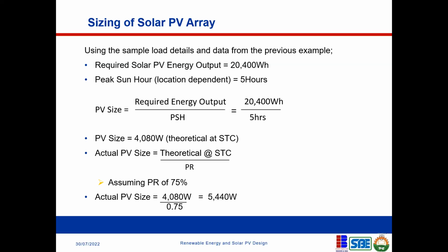So their performance drops by 0.5%. Some of them can be 1%. So every year, the performance of that PV drops by a certain percentage. The equipment manufacturer will always provide this information. It is not the same for every PV model. These are the things you look at when buying PV modules for projects. You look at the one that has the least degradation over the period.